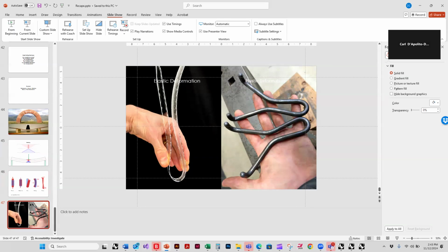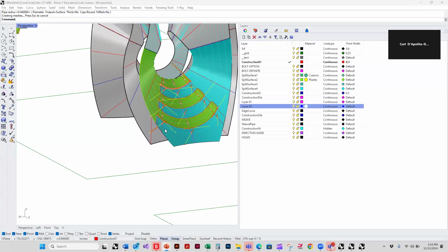And I went through how if you want to fold the metal plastically so it holds its shape, you need to do it around a break, around a point. So if you have a vise, you can put a break in the vise, put the metal in between two pieces of wood that come to a point and fold it over. Or they have a break in the metal shop, but you have to have a point where the metal will fold precisely. So that is the other idea that I went through.